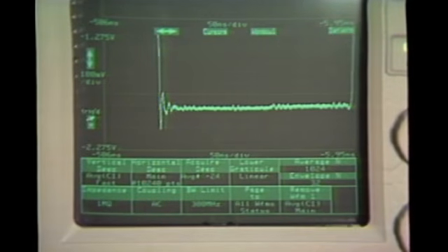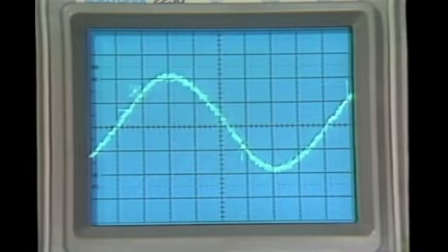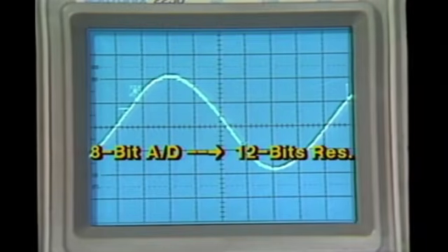More precise because averaging increases the resolution of the measurement if the average result has more digits of resolution in memory than the A to D converter. In other words, the resolution of the displayed signal can exceed the specified resolution of the A to D converter. For example, when using averaging with an 8-bit A to D converter, the measurement approaches 12 bits of resolution.